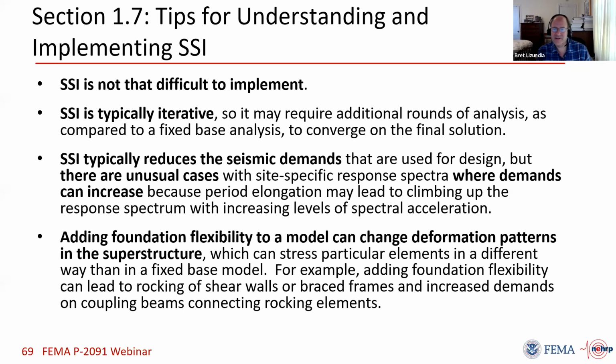It is typically iterative. In a fixed base design, there's only one permutation. But in a flexible base analysis, you might have to iterate a couple times until something converges. So that takes more effort. I'm not trying to claim that this is so easy that it's equal to fixed base. That's not true. It's definitely more work.